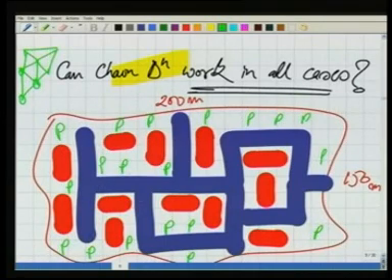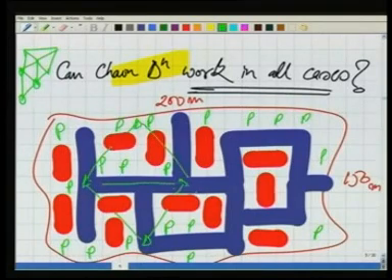But ensuring intervisibility here is really a problem. For example, let's say I take this as one station, another station. Where should I take the third station? These 2 are visible. Can I take the third here? I cannot, because this building is obstructing the line of sight. Here also it is obstructing the line of sight. Here also. I cannot take anything here. So making a net of triangles in this figure is really difficult.